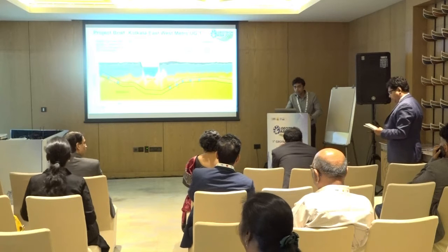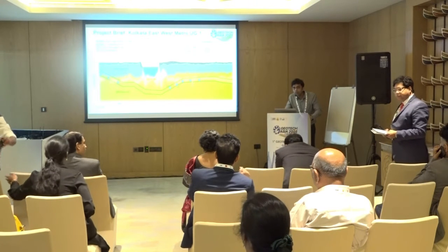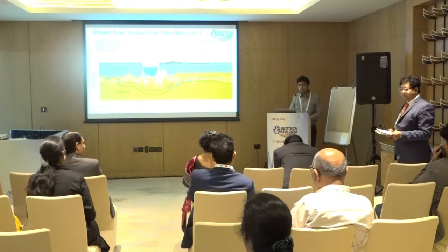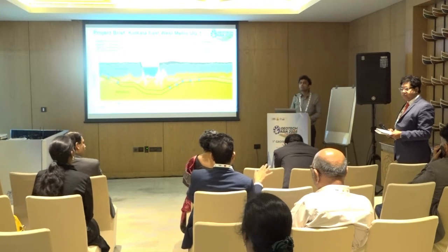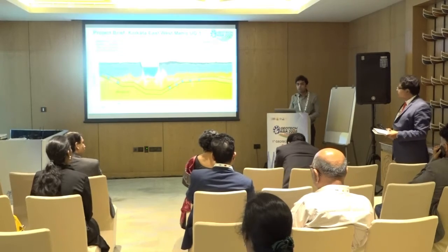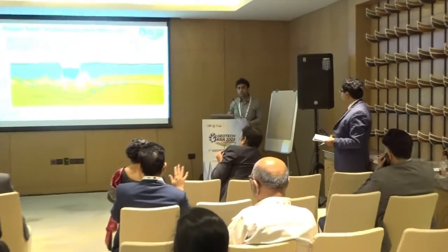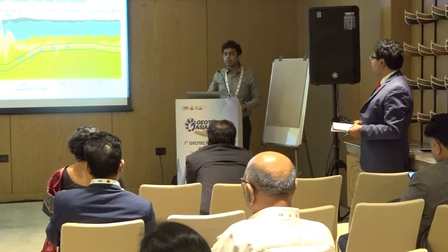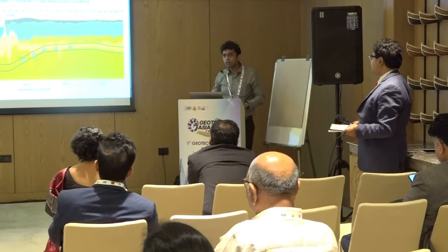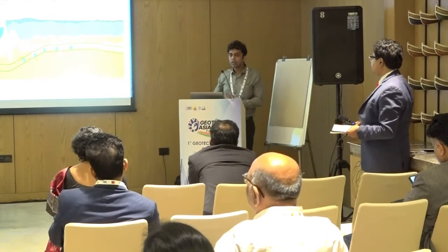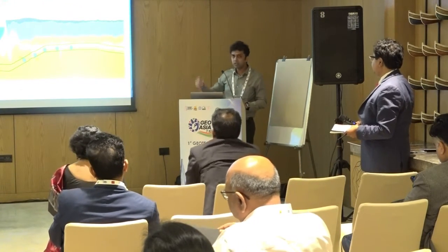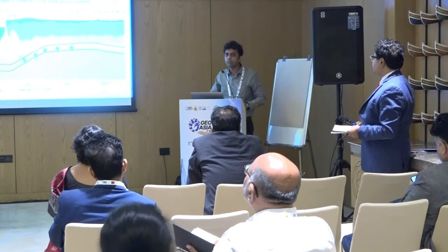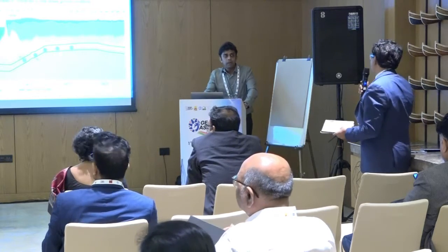Was there a design need of doing a combination of both forepoling as well as soil improvement, or was it a safer approach adopted by the organization? It was a matter of abundant precaution, because we were constructing underneath, so it was the safer proposal. Otherwise, this soil improvement was enough. Yes, through the validation, that is one of the points I'm trying to make, that ideally it was safe. Particularly in the CP1 location that might have been relevant, but beyond that I think it would have sufficed.